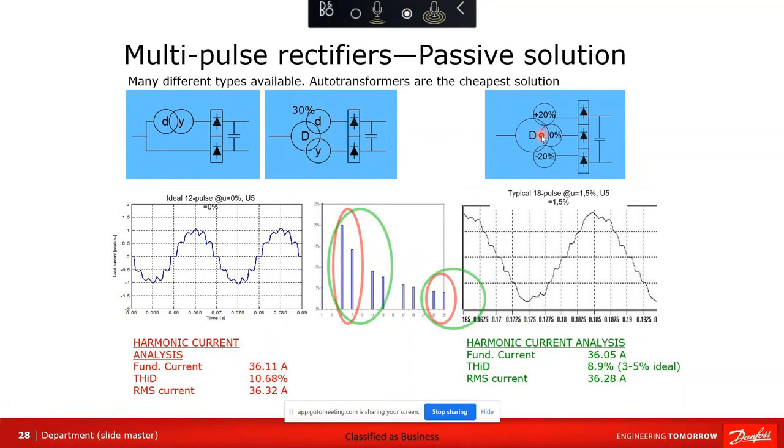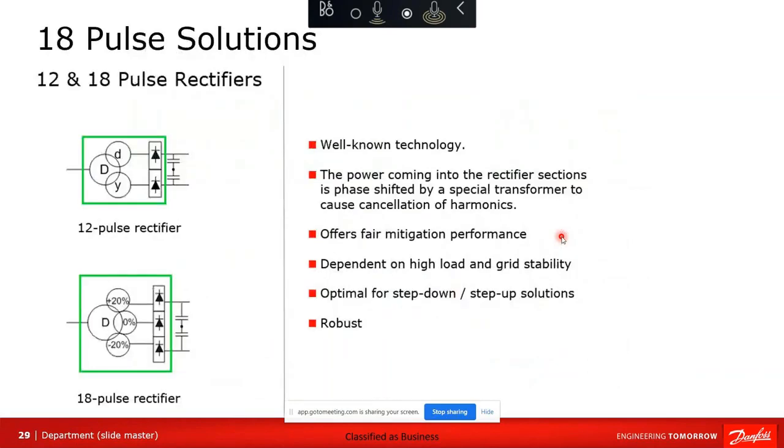And it's based on the fact that the 3 wires coming in are equally balanced. Minimal voltage distortion, minimal phase imbalance. When I say minimal, less than 1 to 2%. If you get 2 to 3% voltage distortion or phase imbalance on the inputs, this curve goes off the charts. I'll show you what that looks like in a minute.